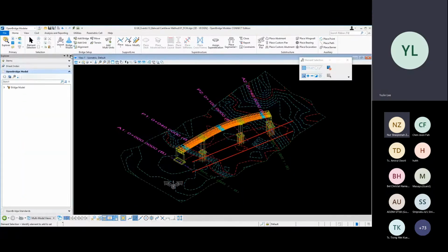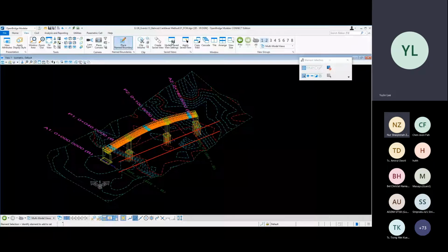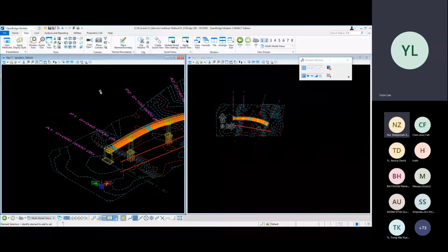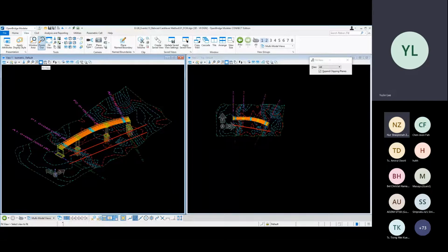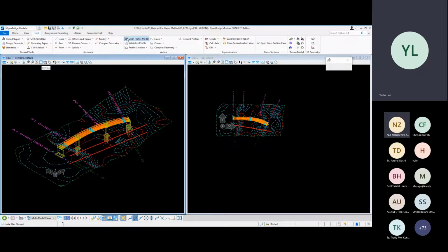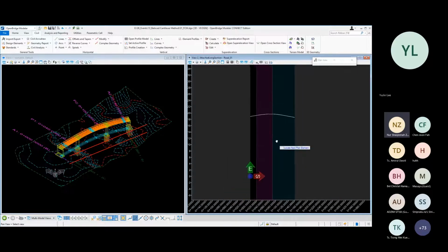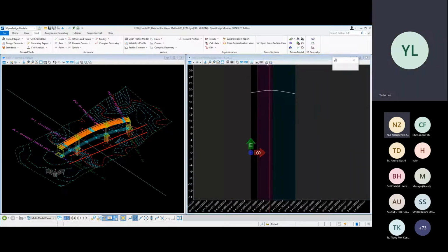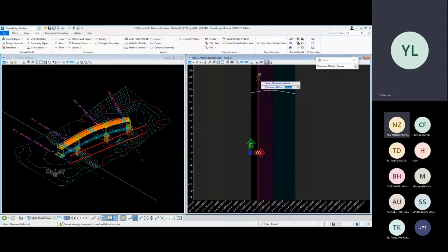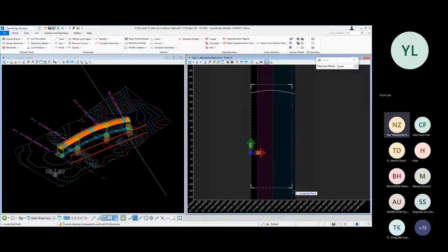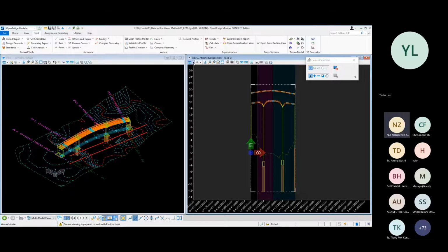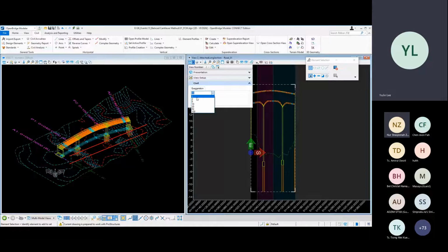I'm done creating the physical model, but we have to verify the elevation of the footing top because the real terrain model will not be flat. So move to open profile model on the civil tab and open the profile for the vertical alignment. And select the 3D cut button to produce a 2D drawing based on the 3D model. And then change the exaggeration scale.